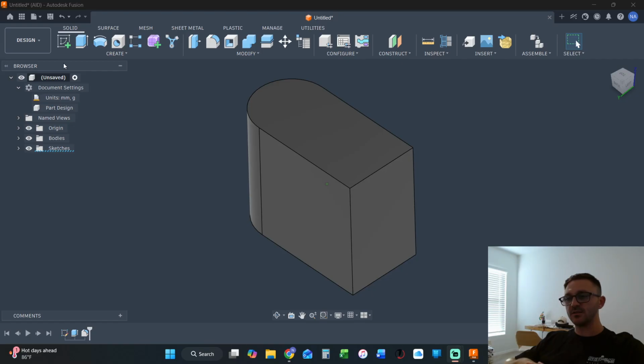And what I mean by flat is it doesn't have to be parallel, it doesn't have to be horizontal or vertical. It can be in any orientation it wants. By flat, and this is going to be covered when we go over GD&T, I mean there's no peaks and valleys. It's just a perfectly flat, smooth, even surface. It's like a piece of glass, but you can hold it in an orientation you want. It's still flat. It's infinite, though, in both directions.